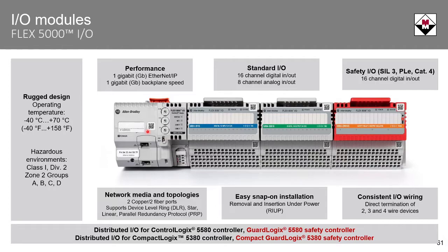The high-performance digital I/O modules support less than 1 millisecond screw-to-screw response time and up to 200 microsecond RPI. The modules also offer counter functionality, input events, and scheduled outputs. The analog I/O modules support a less than 5 millisecond screw-to-screw response time and up to 200 microsecond RPI.